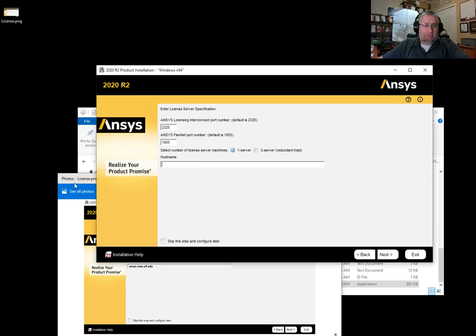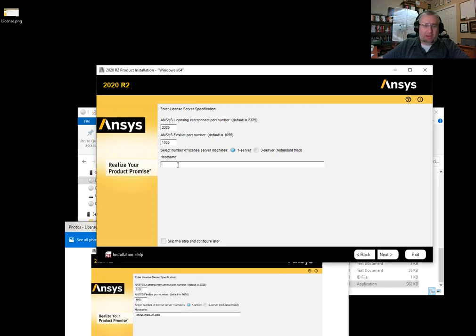Yep. Okay. And now I'm going to copy the host name, which is ANSYS.MAE.UFL.edu. This is the teaching license server in the Mechanical and Aerospace Engineering Department here at UF. I want the one server configuration, and let's hit next.